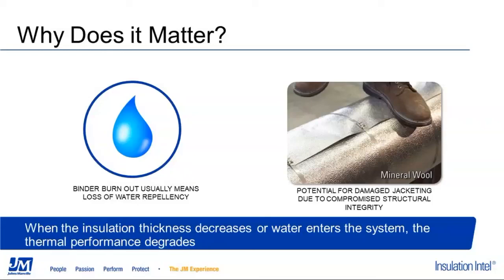So between the water and the loss of the compressive resistance, both of those will have a negative effect on the thermal performance, because obviously you will be talking about less thickness. And then the water is a great heat conductor, so you're going to be losing heat performance with that as well. So now that we understand what's the big deal about this, what can we do about it?